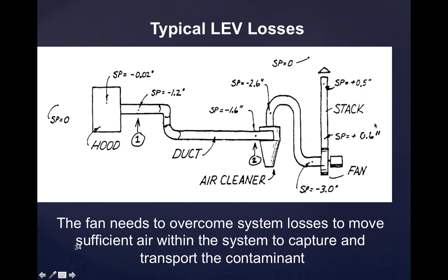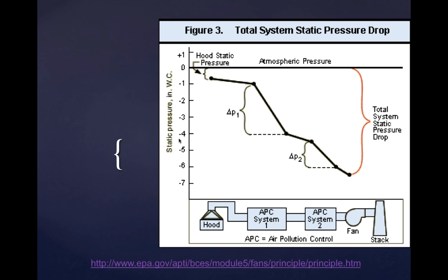Static pressure outside of this whole system is zero. Static pressure out on the exhaust system is always positive. Notice how it goes down here. It starts at 0.6 inches right outside of the fan, 4 to 6 duct diameters outside of the fan, and then it reduces to 0.5 inches because you've lost energy in this vertical run of ductwork going up, right? So even on the discharge side, you're losing energy. Really, we design the business end of this thing as a suction side, so that's where we're designing from most of the time. This diagram represents the static pressure.